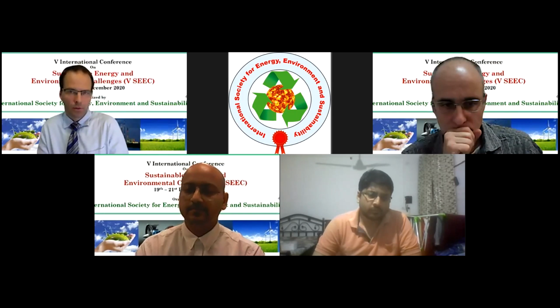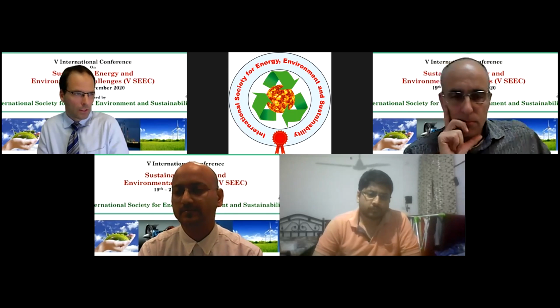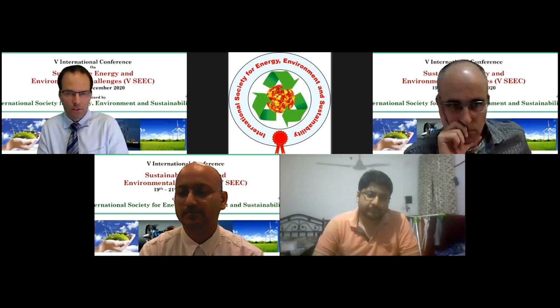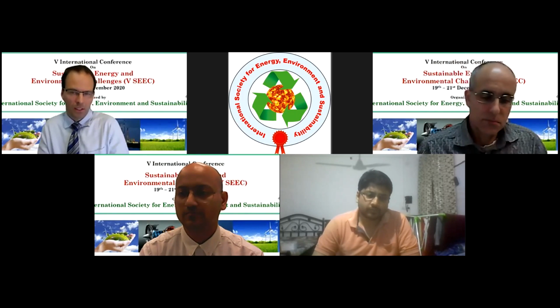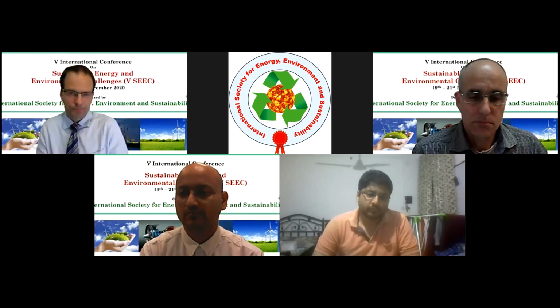And I also agree with you, Professor Singh, that it all depends on your water quality. You don't need RO if maybe you're only wanting to remove some viruses or bacteria, and then maybe UF is enough. So I think it really depends on the water quality and what water quality you desire.